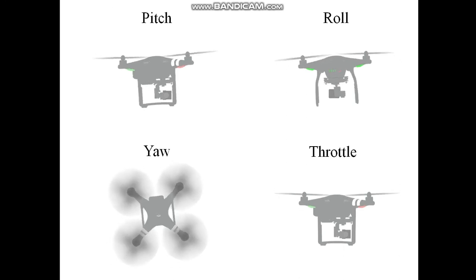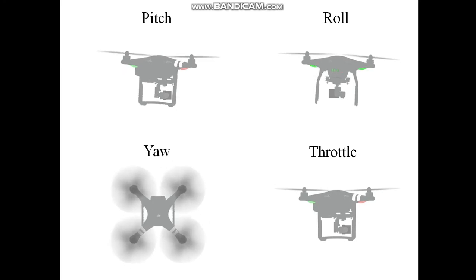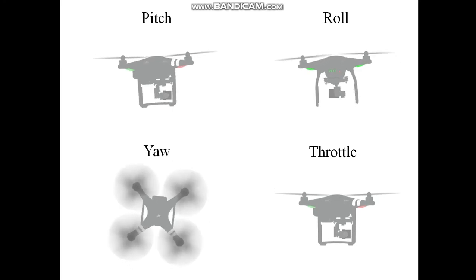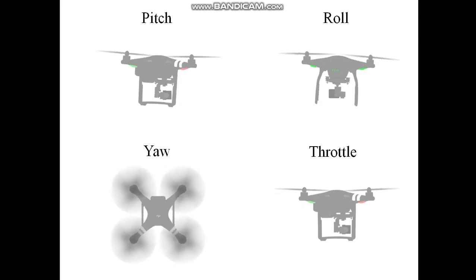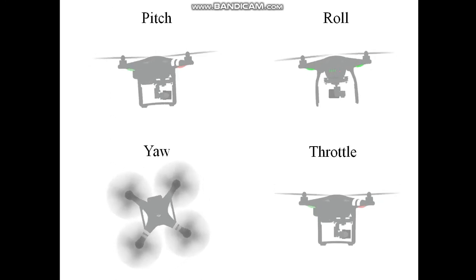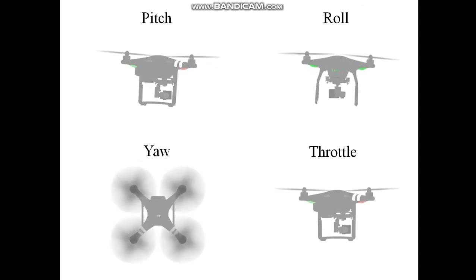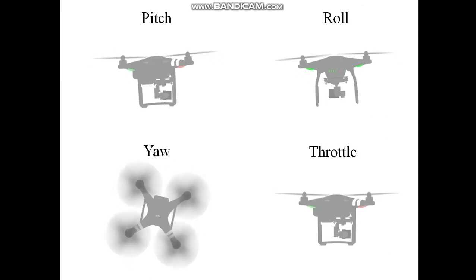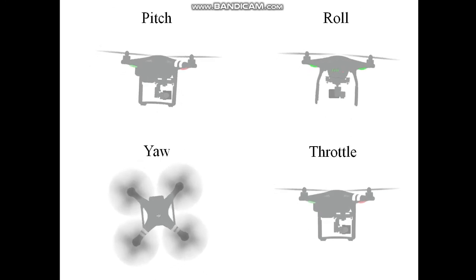Since similarly rotating propellers are located across from one another, speeding up or slowing down both produces no roll or pitch body movement. Since two have sped up while two have sped down, the net thrust also remains constant, thus no change in vertical acceleration. The last controlled vehicle degree of freedom is the vertical throttle. It is the simplest of the four and is controlled merely by speeding up or slowing down all four propellers equally.